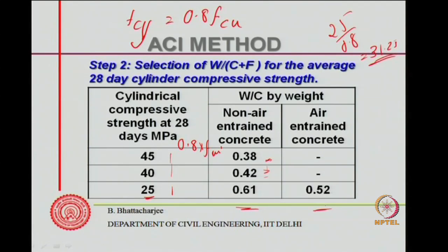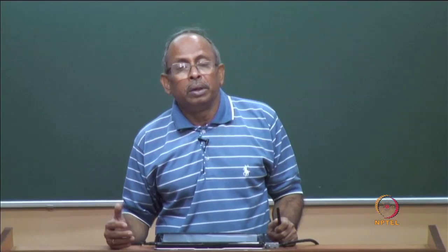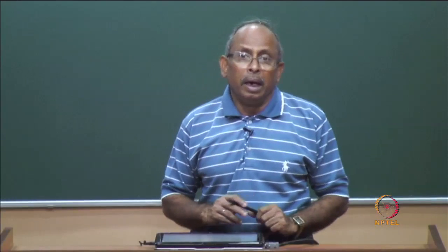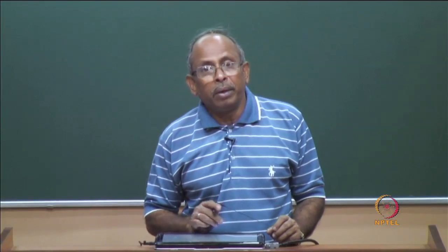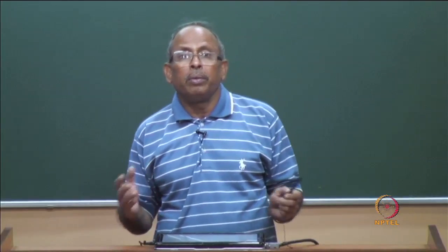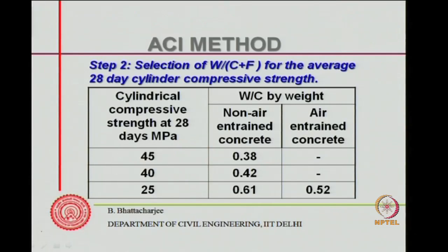air entrained concrete. Largely, of course, in India we do not use air entrained concrete except for Himalayan region, where air entrainment becomes a must, because deterioration due to freeze thaw action is possible in the Himalayan cold region. Otherwise, generally non air entrained concrete is what we should be using. So, here the water cement ratio is straightforward, obtained from the table.